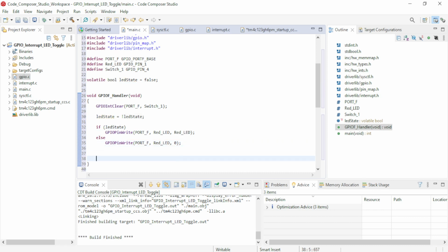One more important factor, I told you that whenever we press the switches, they make multiple contacts and we call them key bouncing. To avoid key bouncing, we can use a simple approach. First simple approach is to generate a delay after any key press. Okay, and we call it software delay. So introduce a delay to handle key bouncing.